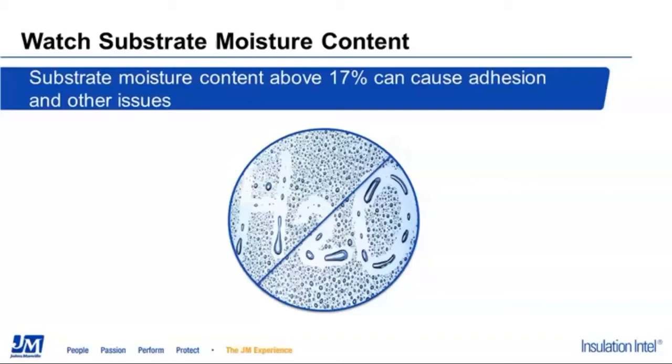However, there's a multitude of moisture meters out there and available. What we would like to do is see guys, particularly in wet or moist or humid climates, southeast, we'd really like to see guys having those tools on the job, looking at moisture content in the substrate, and then evaluating whether or not that's impacting the adhesion of the cell structure.